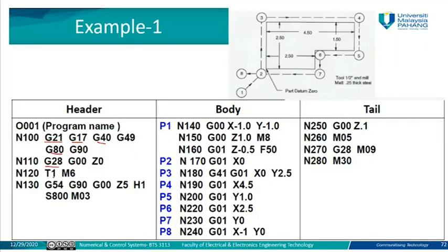The tool that you are going to use, we have only one tool for milling, so we are going to use one tool. Then we have to define these other settings before the movement for the first operation at point one. So you need to see what type of coordinates, what is the rotation speed of the spindle, and what is the compensation for the spindle.